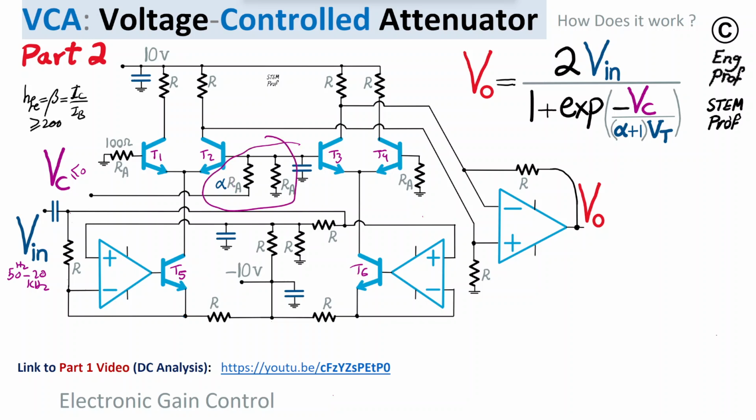So basically we have a resistor division for the V control applied at the input of the circuit at this node, and Vt is the well-known thermal voltage for the p-n junction of the BJT transistors that you see in this circuit, in which Vt is the well-known kT over q, k the Boltzmann constant, T the junction temperature for the p-n junction of the bipolar transistors as shown, in Kelvin, and q the electron charge.